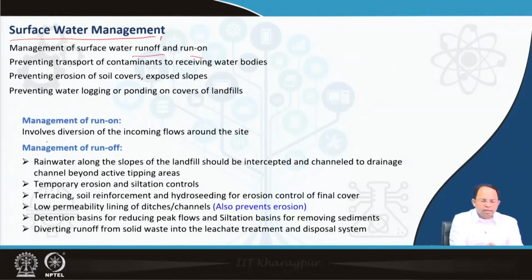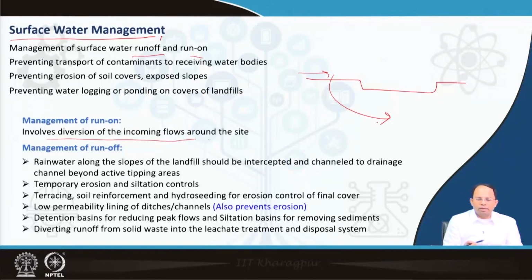To prevent that, we have to divert the incoming flows around the site. If I have got my landfill site, I cannot allow water to move over here. So I have to divert it around the landfill site, right? The other is, of course, the management of the runoff part, which is more important because this is where the water is going inside. We have to prevent the water to go inside.